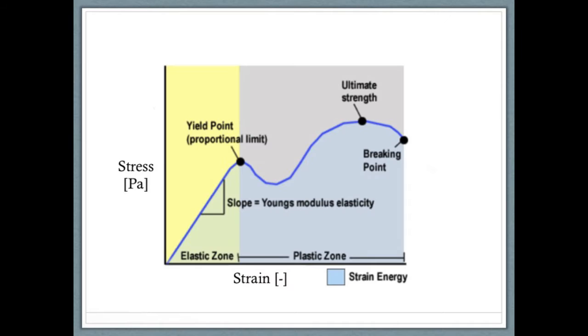But why? To answer this question, we are going to look at the aforementioned stress-strain curve, where strain is represented on the x-axis and stress in pascals is on the y. Each of the terms for the question can be highlighted on this graph. The first term we see, the proportional limit, is shown to be at the end of the linear portion of this graph. It is defined as a transition point between elastic and plastic deformation, or the highest stress at which stress is directly proportional to strain.